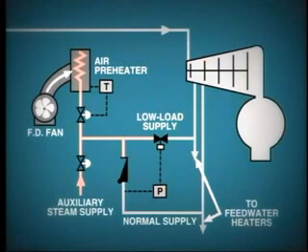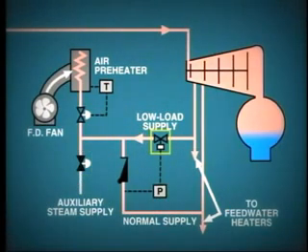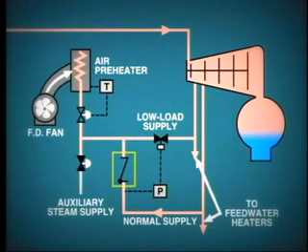Each of these control valves automatically opens in the correct sequence. That is, 1, the auxiliary steam supply during startup; 2, the first stage steam extraction during low load; and 3, the second stage steam extraction at high load.